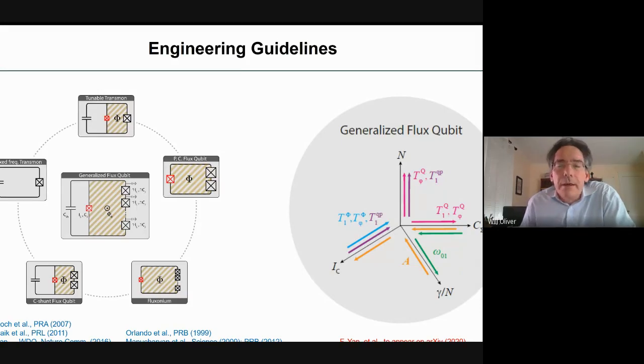And there are. And so what's shown on the right is a multi-dimensional phase space, such as the critical current, the total capacitance, the number of junctions n, this area ratio gamma normalized by n, and the various parameters that we design towards, like anharmonicity and the sensitivity to noise and qubit frequency. As you increase along any of these axes, the arrow indicates the direction of increasing, say, anharmonicity. So as you increase gamma over n, anharmonicity goes down, and so on for all of these.